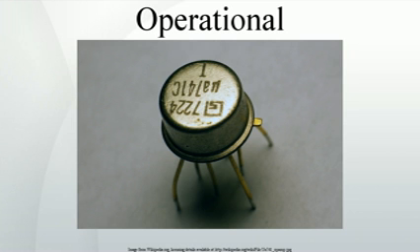Overall open-loop voltage gain. The net open-loop small signal voltage gain of the op-amp involves the product of the current gain hFE of some 4 transistors. In practice, the voltage gain for a typical 741 style op-amp is of order 200,000, and the current gain, the ratio of input impedance 2.6 MΩ to output impedance 50 Ω, provides yet more power gain.